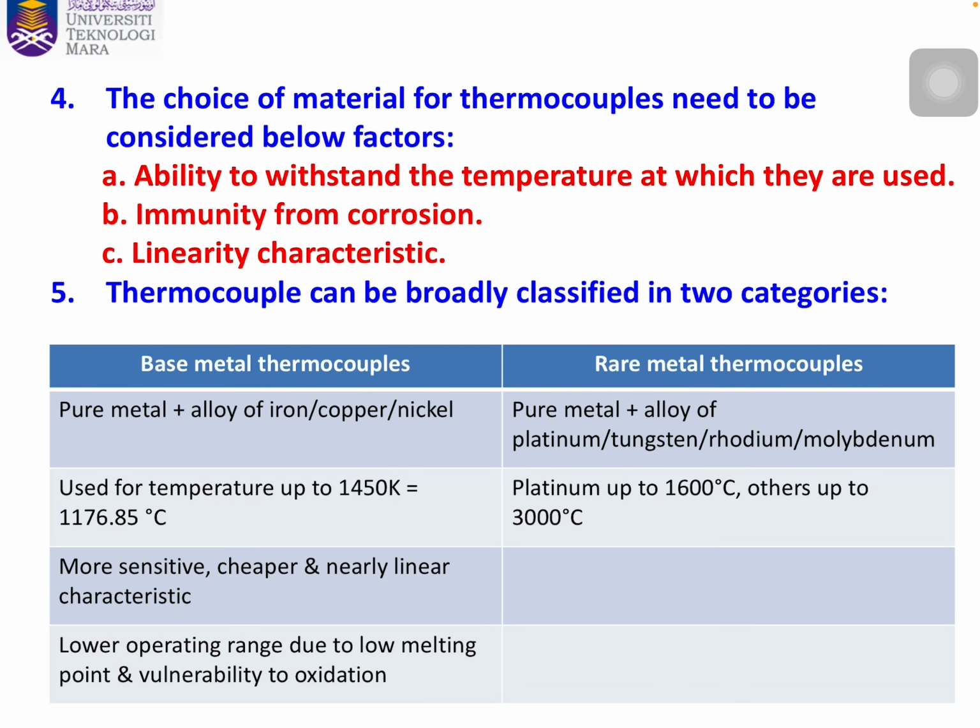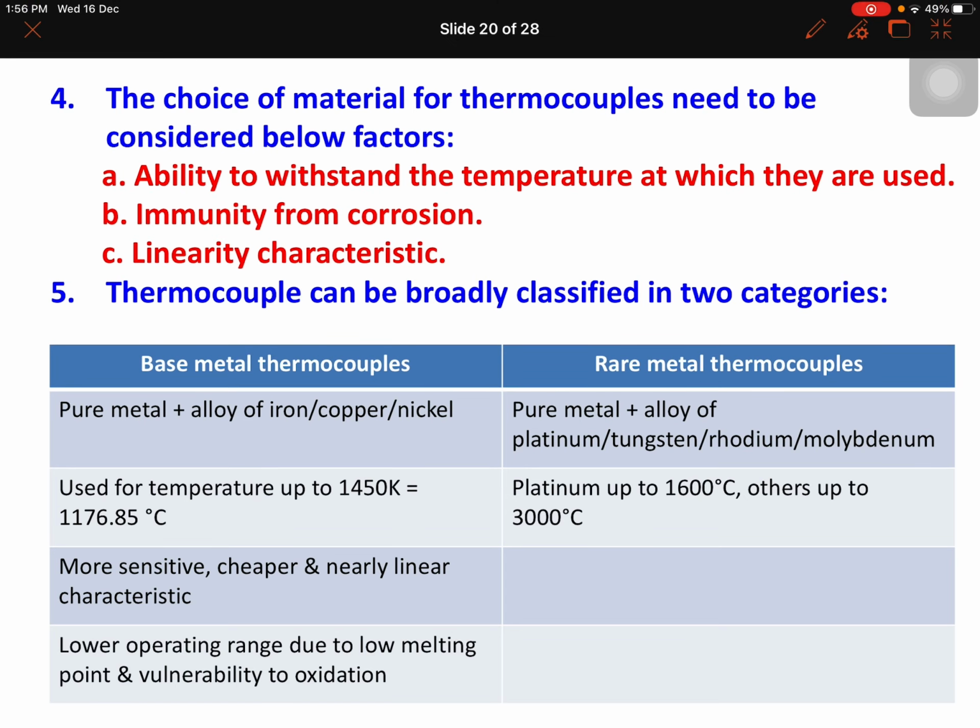Next, the choice of material for thermocouples needs to consider the factors below. First, ability to withstand the temperature at which they are used. Second, immunity from corrosion. And third, linearity characteristic.